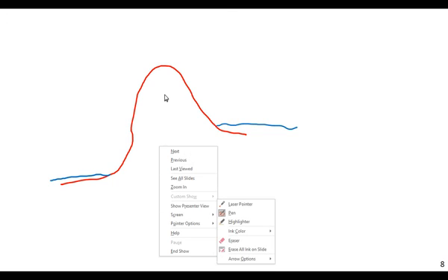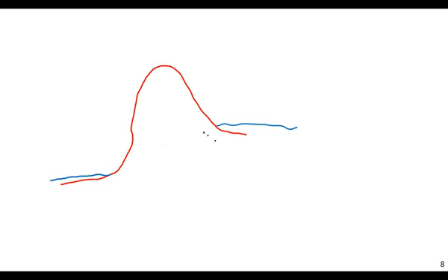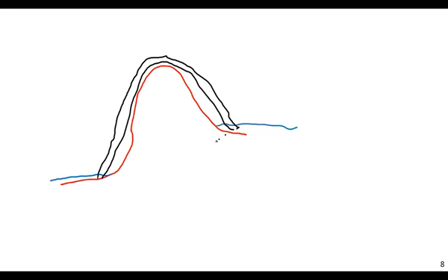You can't just rely on air pressure to get that water over the mountain initially. I don't know whether this would actually work, as it would depend on the specifics. Basically, you want a pipe going over the mountain. This is not to scale. You can't just pull air on this end and have air pressure push the water up the column a mountain high. This thing might be a mile or two high. If this is 10,000 feet, there is no way you're going to push a column of water that high relying on atmospheric pressure.